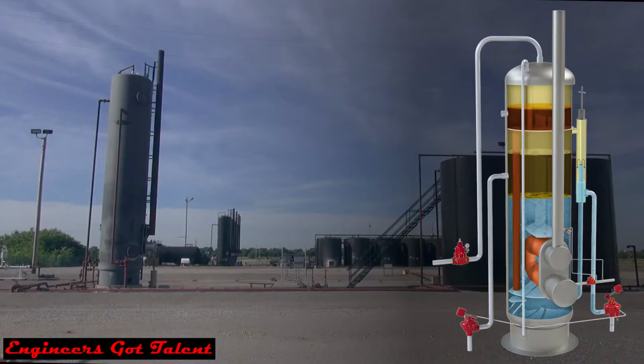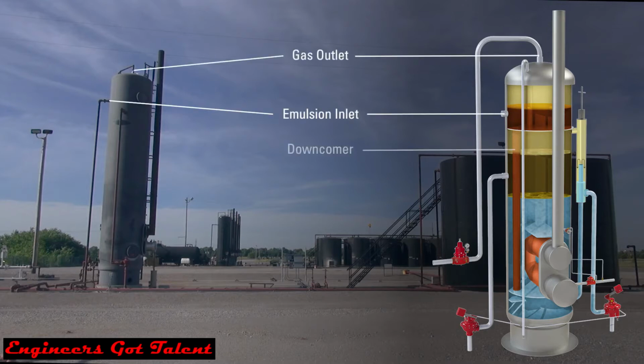Once the emulsion enters the heater treater and the gas breaks out of the top, there is a downcomer that funnels the fluid to the bottom of the treater. And at that point, the emulsion starts to break loose as a result of heat applied to the processed fluid. That processed fluid then relaxes its molecules and the oil and water separate more naturally by themselves. The oil, being lighter in gravity than the water, will float on top of the water.